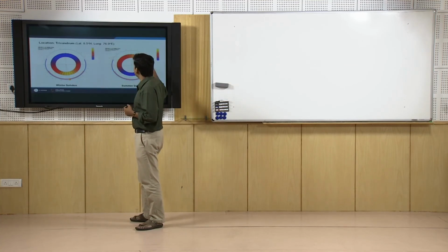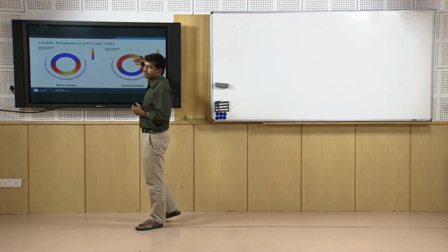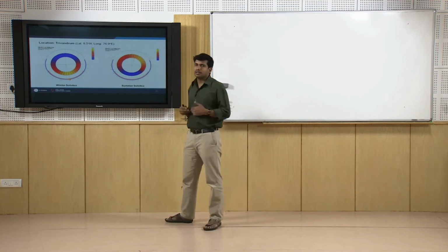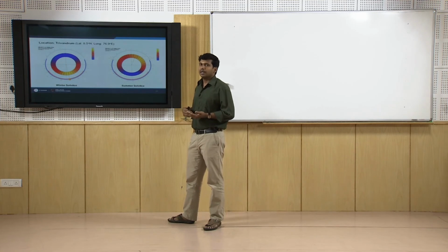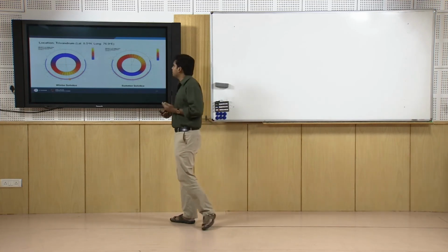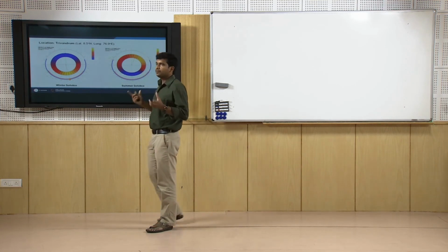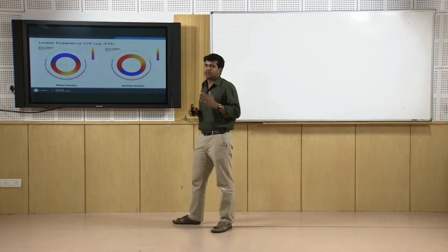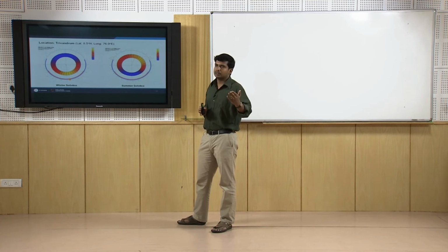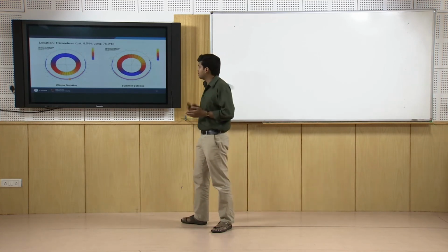If your building facade is this, you will still get solar radiation on your northern facade for at least 4 months for latitudes south of the Tropic of Cancer. The further you go towards the equator, the more it gets. Especially on the equator there will be equal distribution: half of the year the sun will be to the northern side, half of the year to the southern side.